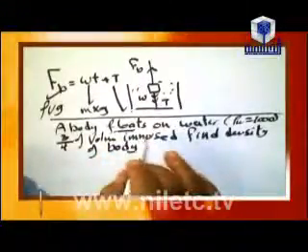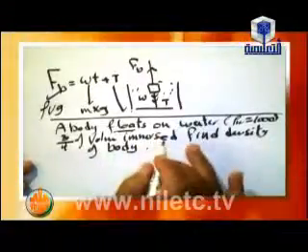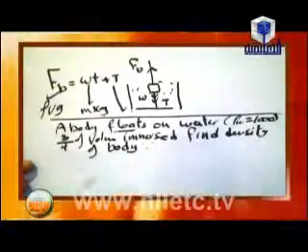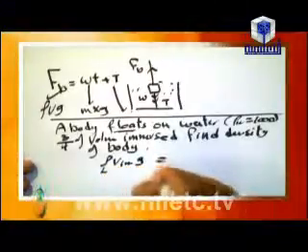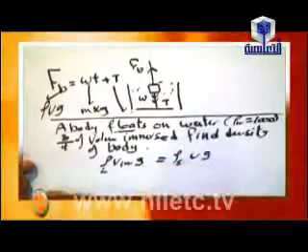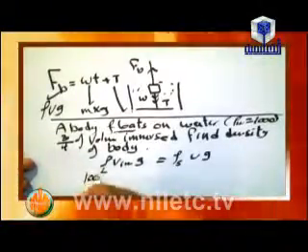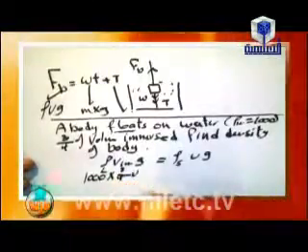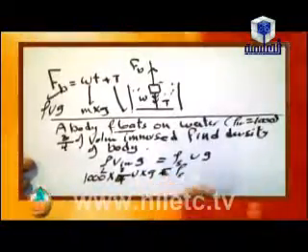We know that the body floats. This is the secret word: float. It means that FB equals rho liquid V immersed g, or FB equals m times g, or rho solid V times g. We can write rho liquid V immersed g equals rho solid V g. This is the case of floating. Rho liquid, which is equal to 1000, times volume immersed 3/4 V times g equals rho solid V times g.